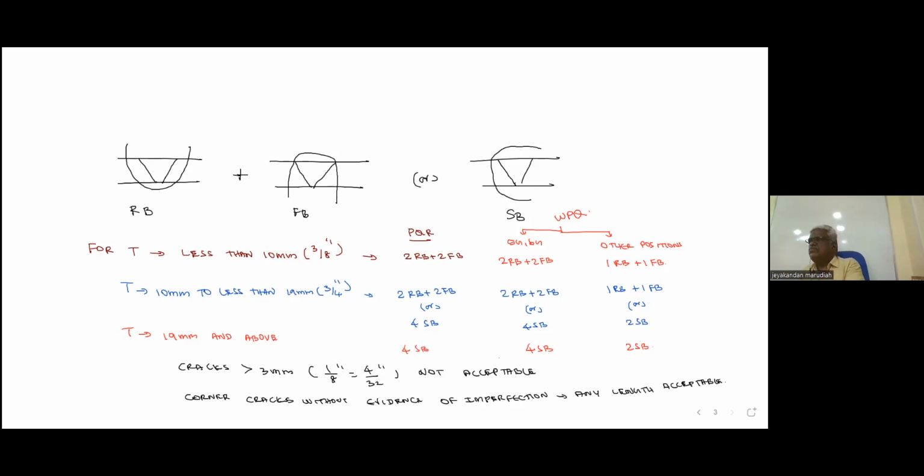Then what about the stainless steel metallurgy. If you take stainless steel, the problems during welding are one called sensitization, another called hot cracking. How to avoid hot cracking? You should have 5 to 20% ferrite in the filler metal to avoid hot cracking.